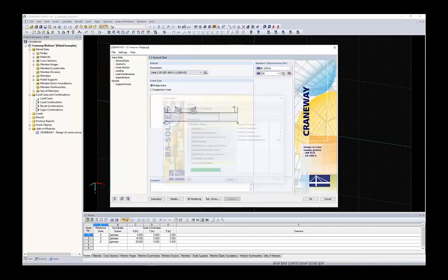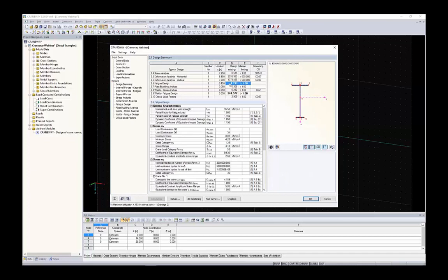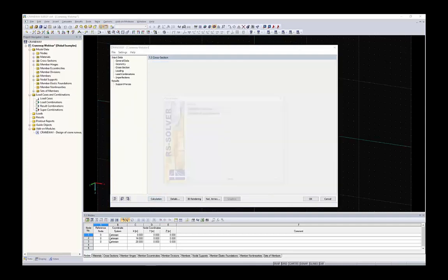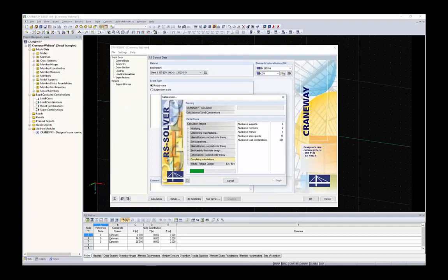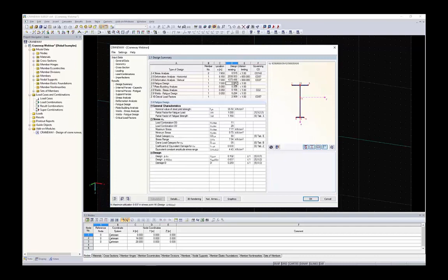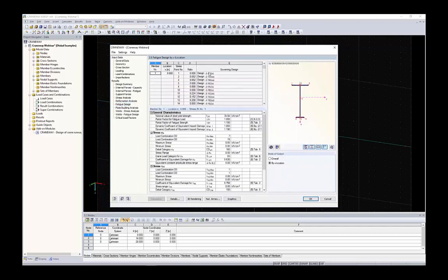This was a small fault because it's still overloaded. I changed the type of the weld on the bottom, but I want to have it on the top of the web. Run the calculation again. And now you can see it's fine. Fatigue design over there. We can also take a look in the detail of the fatigue, and this seems to be okay now.